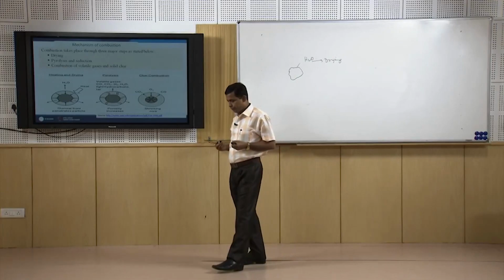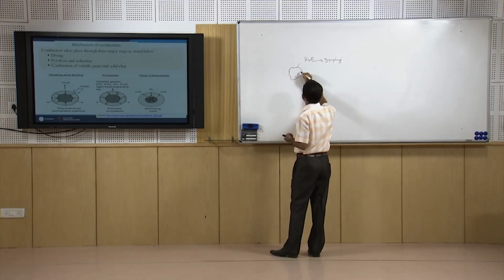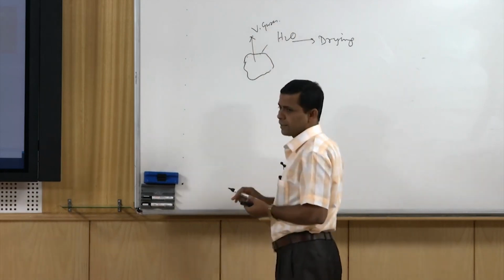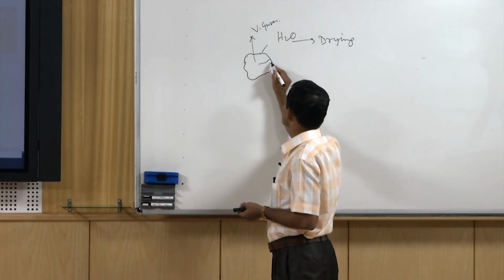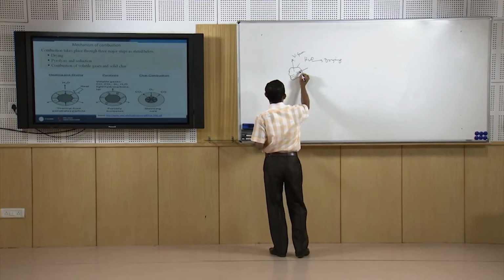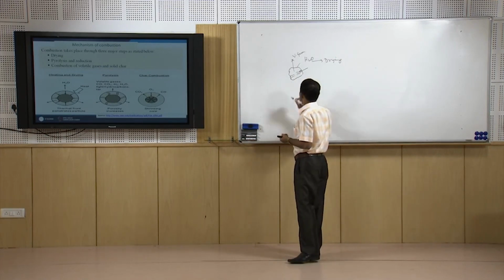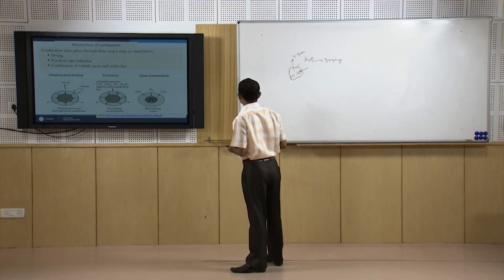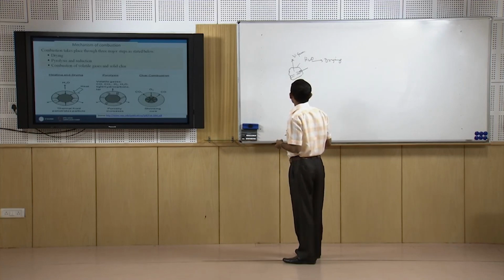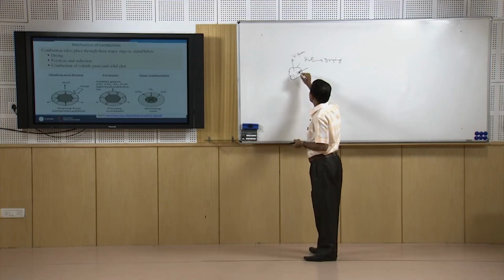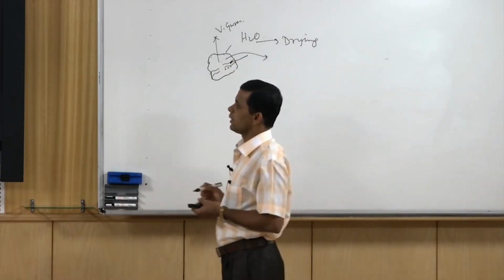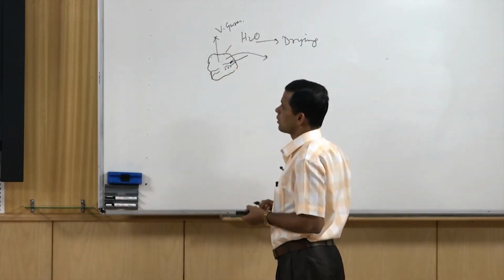Once the drying takes place, further increase in temperature helps to remove the volatile gases present inside the pores, and so the porosity of these particles increases. Once the porosity increases, the air enters through it and reacts with more particles inside, the carbon materials, and then char combustion takes place. So, in this process the first part is drying, the second is pyrolysis. At high temperature the bigger molecules are broken down into smaller ones, that is called volatile gases. So, volatile gases are formed, that is called pyrolysis.